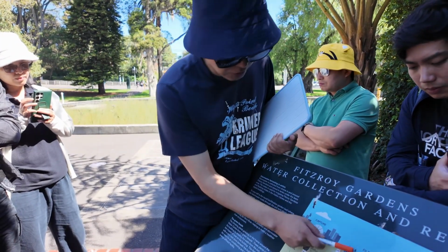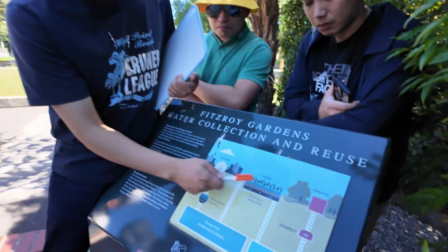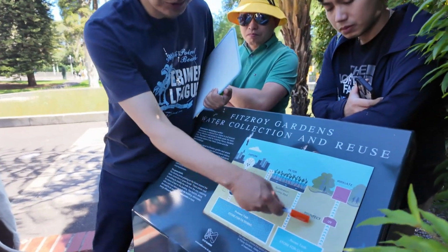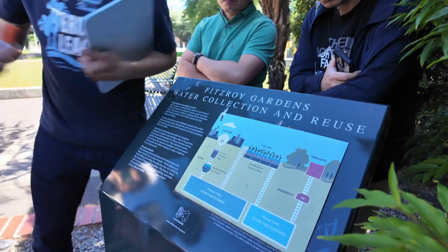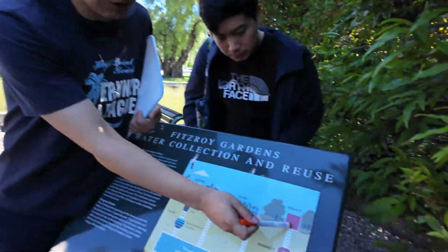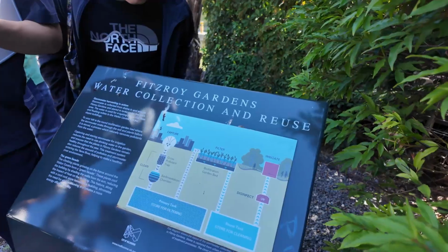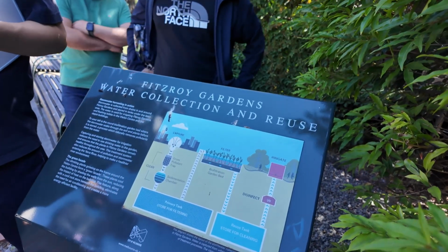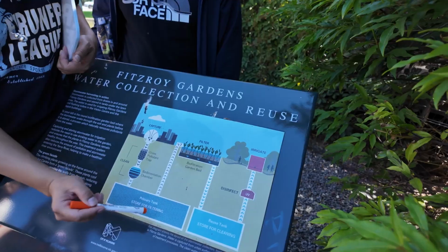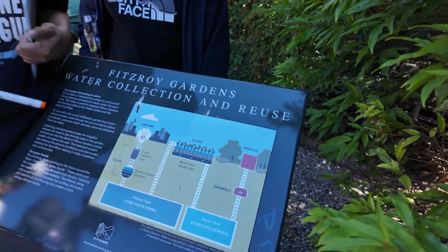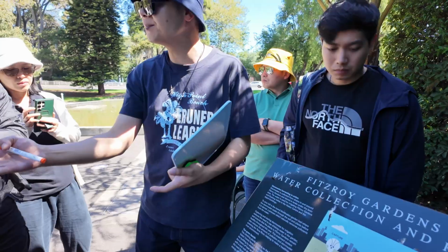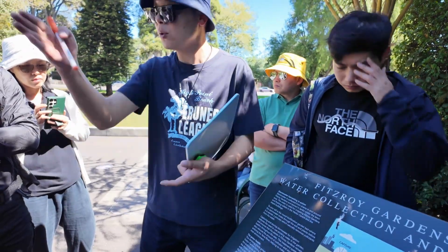And then the water goes through this treatment to filter most of the fine particles, and then to the disinfection, UV, in that room. Then that water is injected into the irrigation network of the park. So you have 2 tanks. Even though we show you these 2 tanks separately, in construction it's built as one, only with a wall separating them. So it's one piece with a wall.